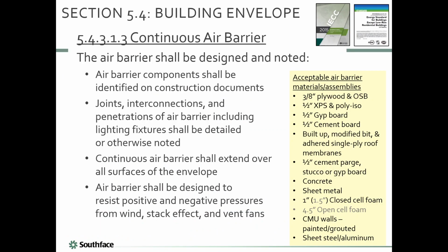Okay. Last thing is air sealing. Both codes kind of, I would say, approach this in a somewhat naive way. They sort of say, if you build with one of these materials, you're probably airtight. And that's a bit naive. It's really more about the penetrations. But they want you to build and have a designated, if you will, surface that is your air barrier, particularly in the walls. And it's got details about, our experience is generally it's penetrations and it's junctions in the envelope. That's where ugly stuff happens.